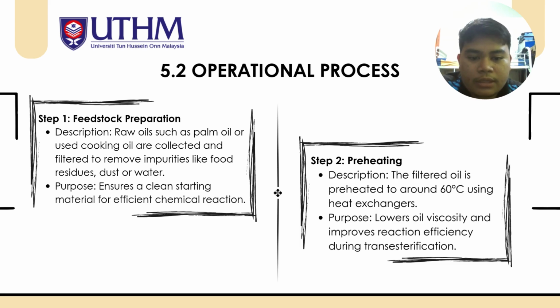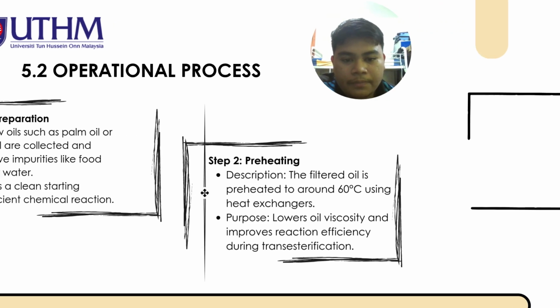The next step is preheating. The filtered oil is preheated to around 60 Celsius using a heat exchanger. It will lower oil viscosity and improve reaction efficiency during the transesterification process.